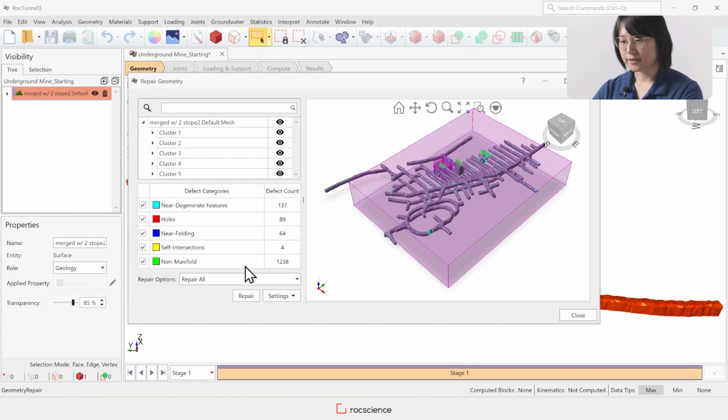So now you can see that the number of non-manifolds has decreased 3 times. And what I would do from this step is to ungroup the geometry at these T-junctions and to delete any unnecessary pieces, or the alternative is to select the pieces you want to keep from the ungrouping and just create a new surface with fewer defects.